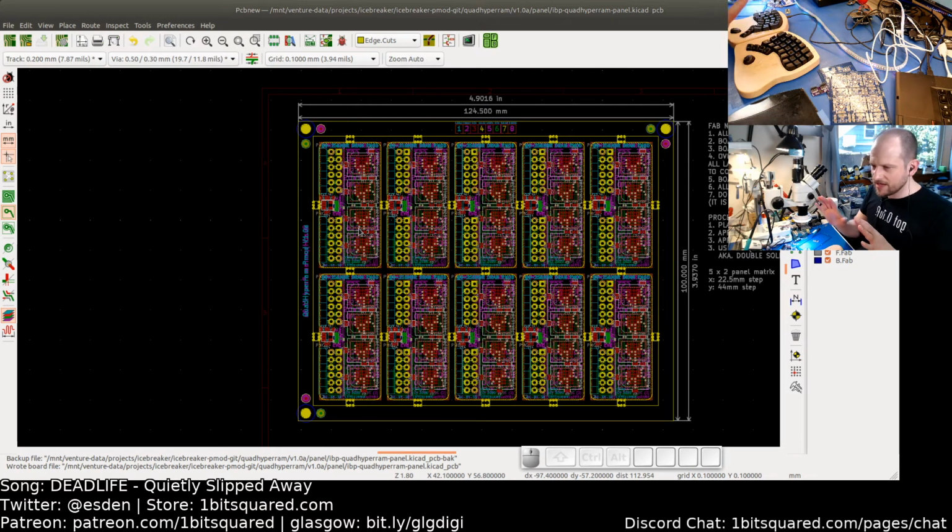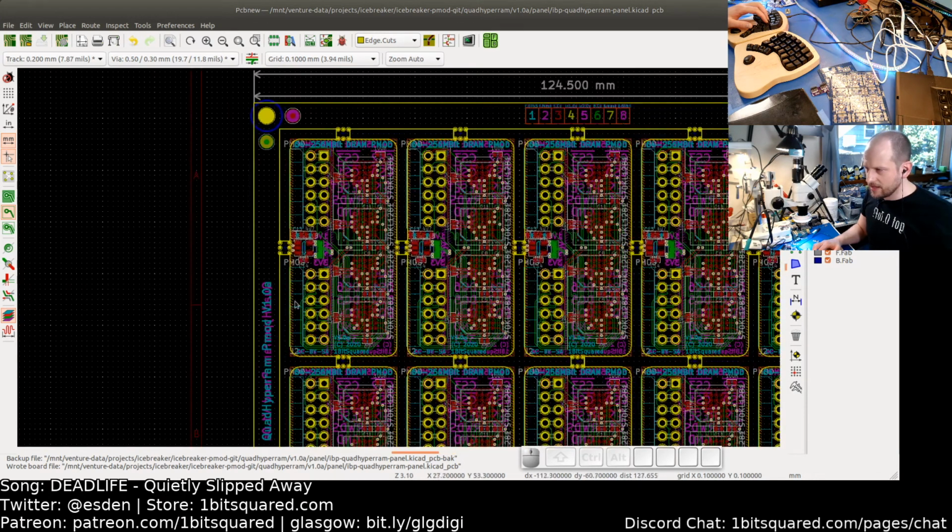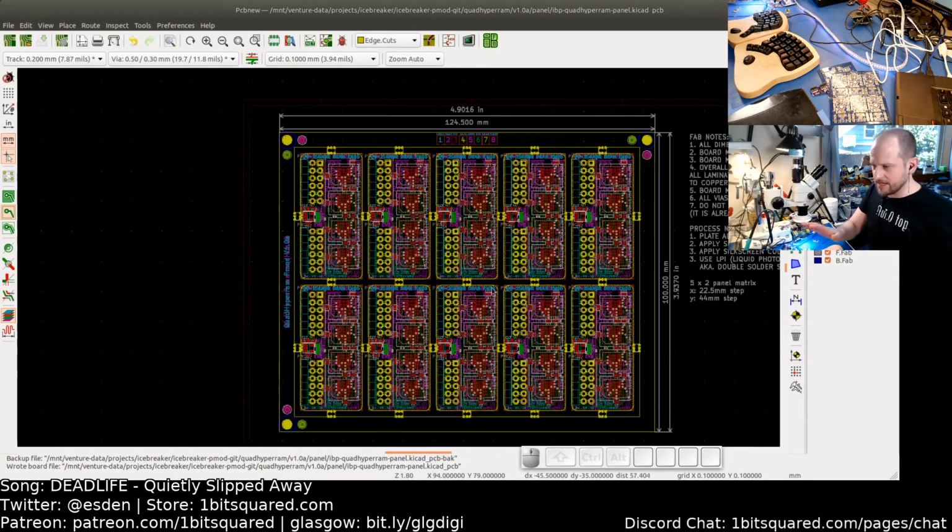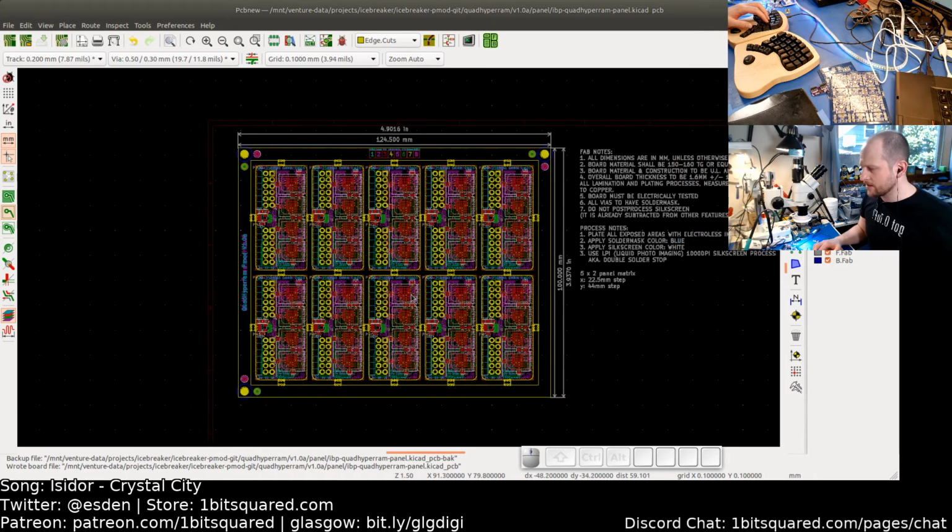So I'm not deleting everything, but some logical things that can be then auto-generated with just importing the board, putting it in the right position, creating the notches in the board outline, and then just make an array, and that's it. So this is the major amount of work is always if you do a new panelization, updating the board with new board design is much less work, and it goes much faster.